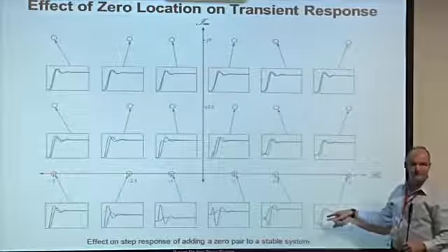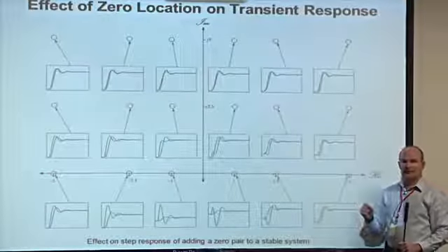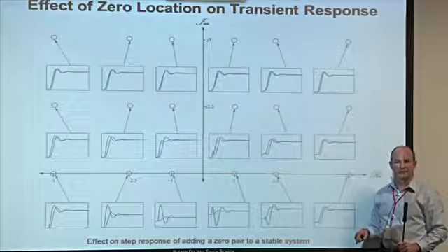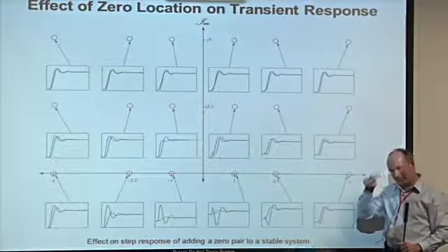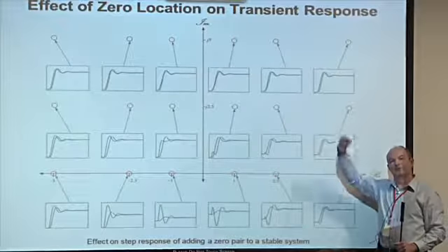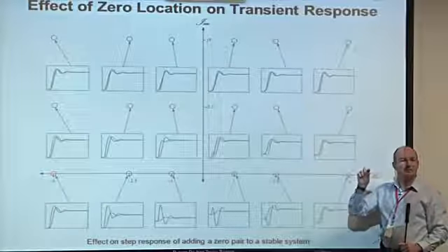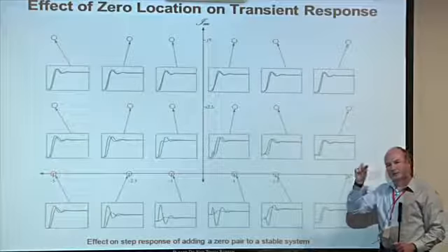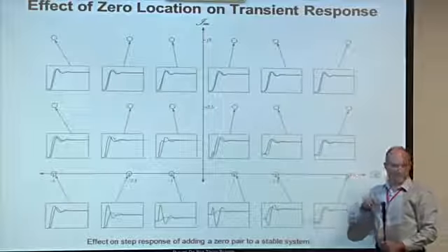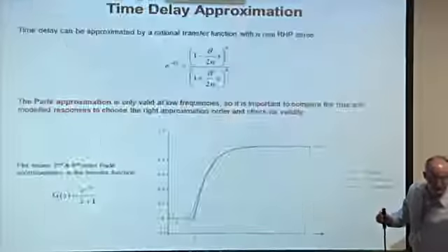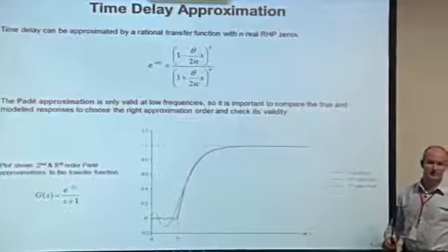That's what's going on. Now, the more right half plane zeros that we add in, the more times it's got to cross that original line. If you have 100 right half plane zeros, it's going to go up, down, up, down, lots and lots of times before it recovers. And as you add more and more zeros in, the amplitude of those oscillations gets smaller. And that allows us to do something rather nice, because there is a well-known approximation called the Padé approximation, which exploits this property.